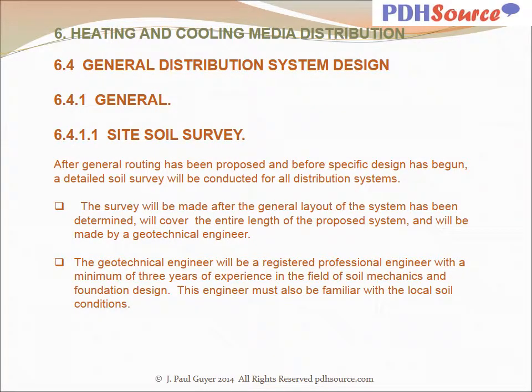General system design considerations. Some aspects of a heating or cooling distribution system design are similar regardless of the system type. These aspects are discussed below. First, site soil survey. After general routing has been proposed and before specific design has begun, a detailed soil survey should be conducted for all distribution systems. The survey will be made after the general layout of the system has been determined and will cover the entire length of the proposed system and will be made by a geotechnical engineer.